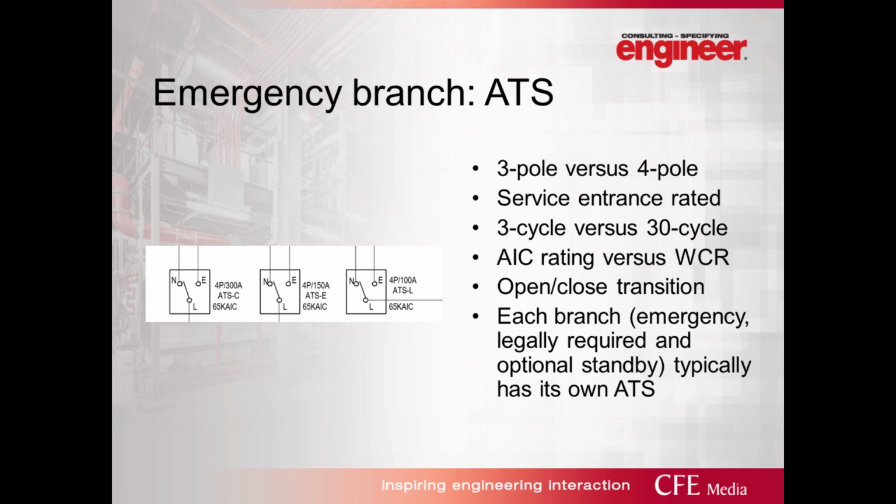The service entrance rated ATS is required when the entire load of the installation requires standby emergency power during the power loss. 3-cycle versus 30 cycles. Just like the switchboards and switchgears, ATS can be 3 or 30 cycle tested. Coordination study is a critical element that must go hand in hand with the design and specification of a safe and reliable emergency power system.